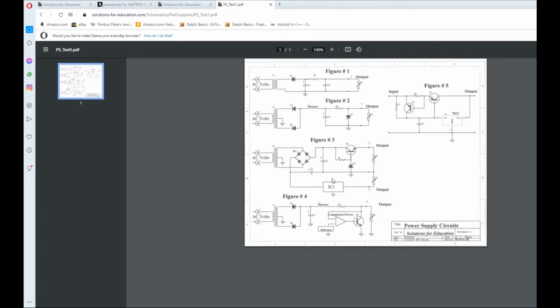That is not the way it is up here in a series regulation. In a series regulation, the current can change all over the place. That is the draw by the load. And this guy here just simply says, well, adjust the voltage for less current. That's all. However, if this guy conducts more, he draws this point closer to ground than to the source. Now, the advantage of this circuit is you can pop the load clear off. And this guy here will say, okay, but you still got 5 volts there. Load or no load, 5 volts. How much current? Well, that depends on what we need.